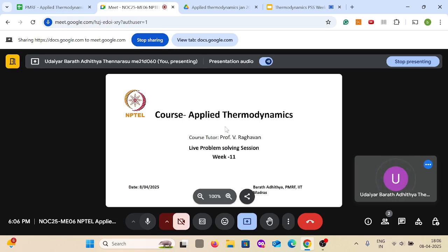And then you have normal shock. So any compressor flow or flow through a nozzle, you assume that it is an isentropic process. But in case of a normal shock, what happens is your entropy will increase. It's not an isentropic process, so you will have a change in properties. So if there is a shock happening, and this will happen mostly for a supersonic condition. This will happen for a supersonic condition.